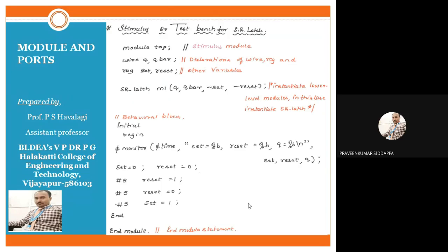First, initially we have written set is equal to 1, and if reset is equal to 1 is mentioned in the second combination, we have mentioned both. But in the second we have not mentioned set, which means whatever we have written previously, that only should be loaded. Or otherwise, if you require both, you can write it, no problem.